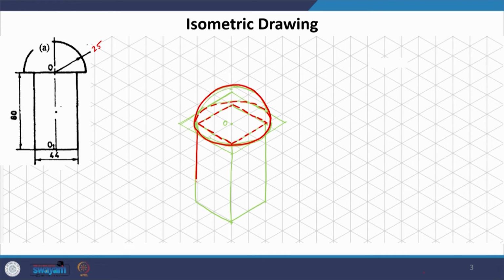And then we see the solid lines. Anything that is visible in the front is seen as solid. Those fundamentals remain the same in both ortho and iso. So, this is what we will be seeing if we convert this orthographic into an isometric.